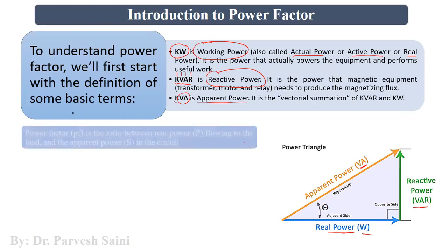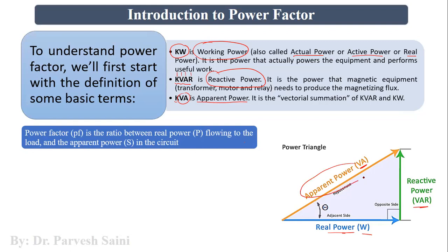Now, what is power factor? From this we can get the power factor, because this apparent power is actually the resultant of two powers, the real power and the reactive power, right? So power factor is the cosine of, if we talk about the same phasor diagram, V and I, the two components of the series RL circuit, and the phase angle between them is phi. So cosine of this particular angle between the voltage and I,